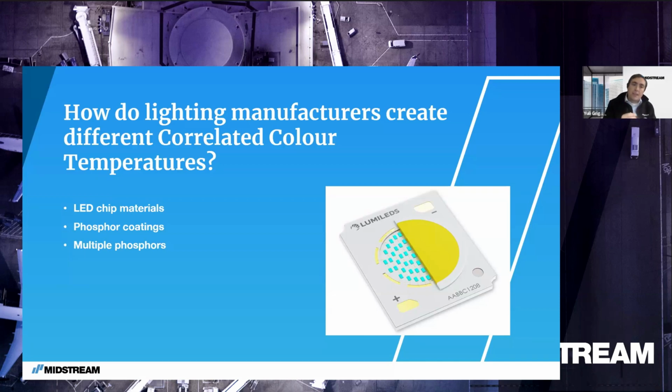And then, of course, we often get asked, or some people think about, how do lighting manufacturers create this color temperature? What do we do as midstream to make 5,000 or 4,000 or 3,000 or even 5,700? And the answer actually is we don't do anything about it. We specify from our supply chain the type of LEDs that we need to employ for that particular scenario. So if an airport orders a batch of floodlights, then we would order from our suppliers of LEDs like Cree or Nichia or Samsung or Lumileds. We would request them to be, for example, 5,000 Kelvin.